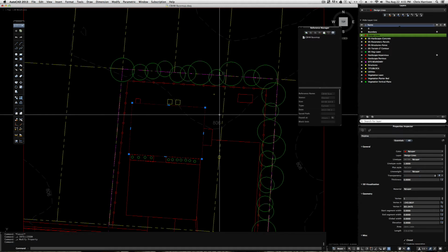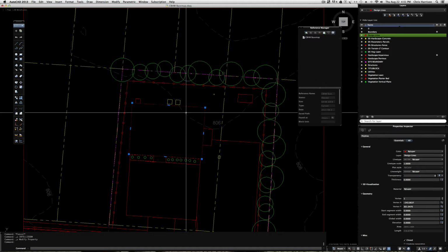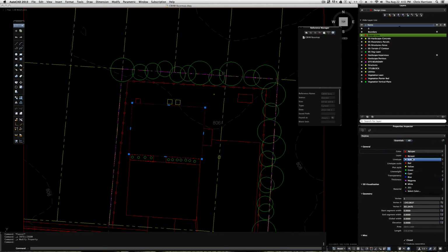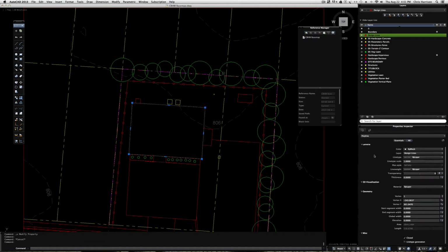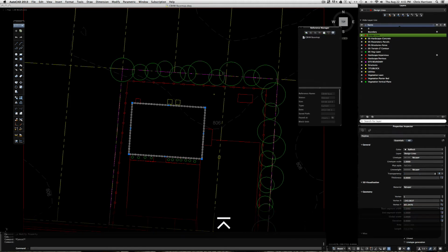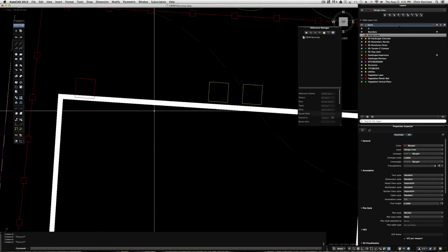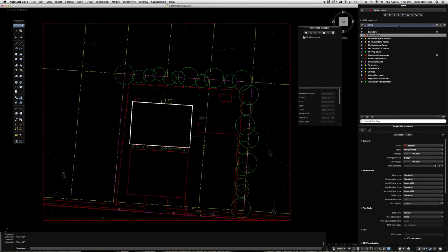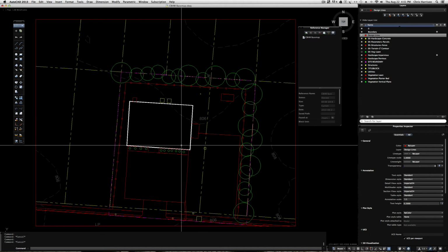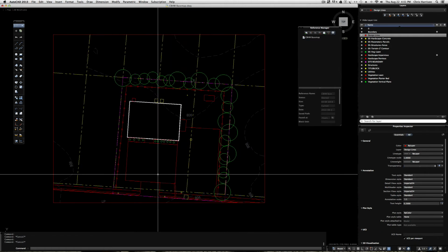this instance. And I'm actually going to make this white. This is our design lines. I didn't distinguish between structures, but we're going to actually make this one white, and I'm making this one white because white will print thicker. And actually, even beyond making it white, I'm going to give that thing a global width. So I'm going to make that 1, and it just gives a line of thickness throughout. So whatever scale it's on, it'll still have that width. And actually, maybe 1's a little big. Let's go 0.5. I just want it to stand out from the other elements because it is the outline of the pad of the home. Okay, cool. Alright, so that's done.